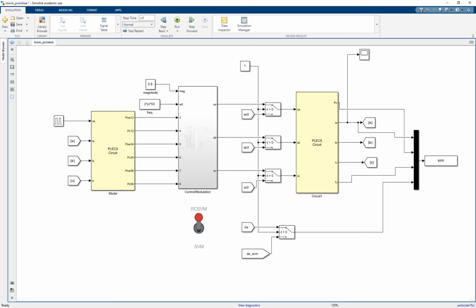So this time I'm going to show you how I did the simulation for the work I put in the description below. The work is about designing an optimized modulation for a two-level three-phase power electronics converter that can actually address the two degradation aspects of SiC MOSFETs. First is the bond wire liftoff fatigue, and the other one, which is very recently known, is gate switching instability (GSI), all in one framework.